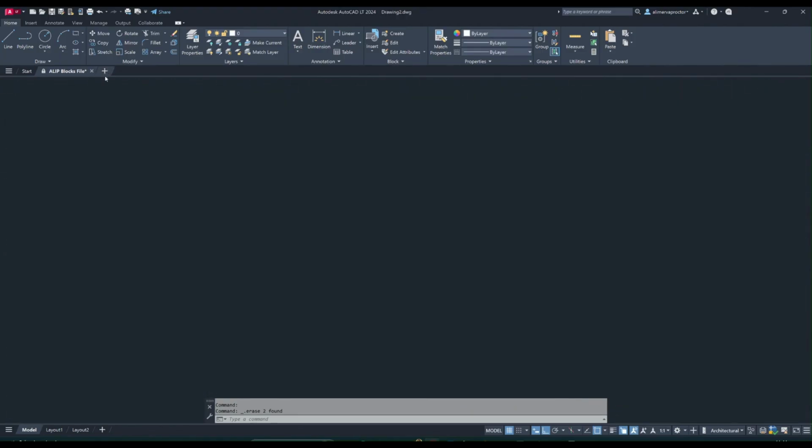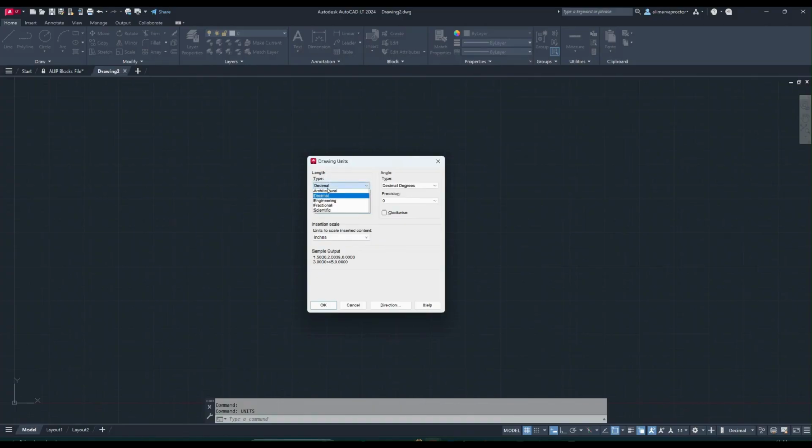I will be teaching you guys how to create these two, making them into blocks, and much more. If you did not have that file set up as yet properly, always make sure your units are set up to architectural, your precision is 1/8. Right guys, make sure of that. In this we might be doing some mathematics depending on the size of our windows, what is left back from our windows, and much more.